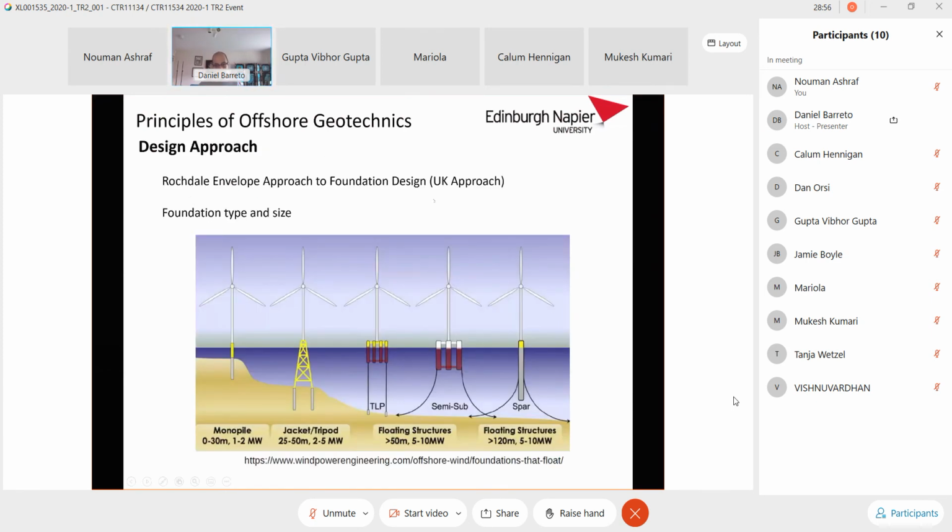The other thing that I go into a little bit of detail on in the pre-recorded lecture is that your foundation type depends, of course, on site conditions and environmental loads, as well as the mechanical components that you may have, for example on a wind turbine, as John's here. But the biggest determinant that enables you to choose the type of structure is the sea depth.